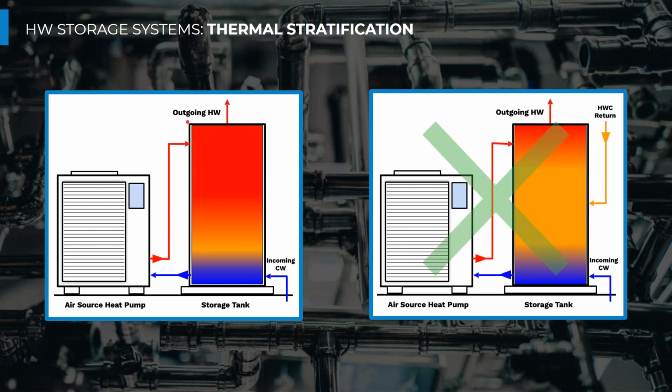This is leading to a very high effective storage volume because we have a lot of water above the usable temperature. So we're using our storage tanks efficiently and effectively in this design with good thermal stratification.